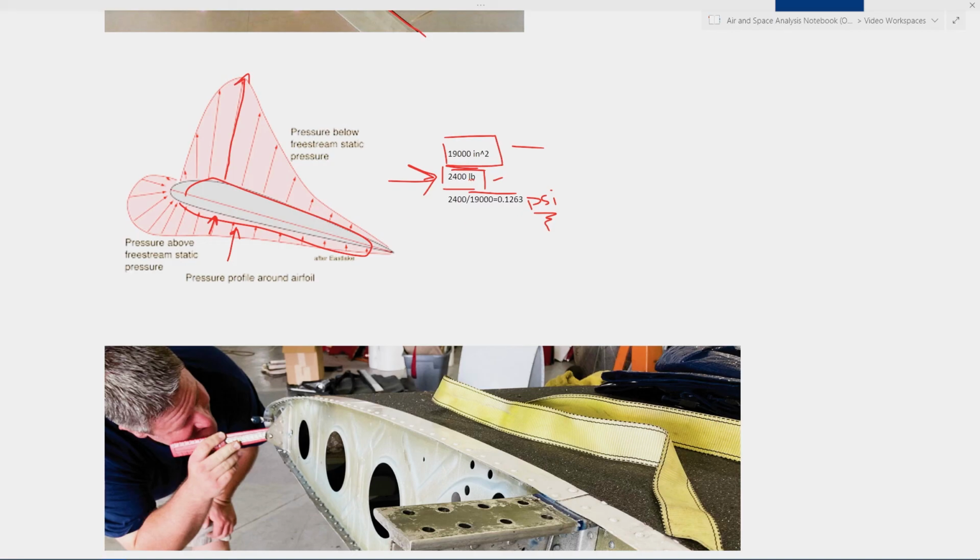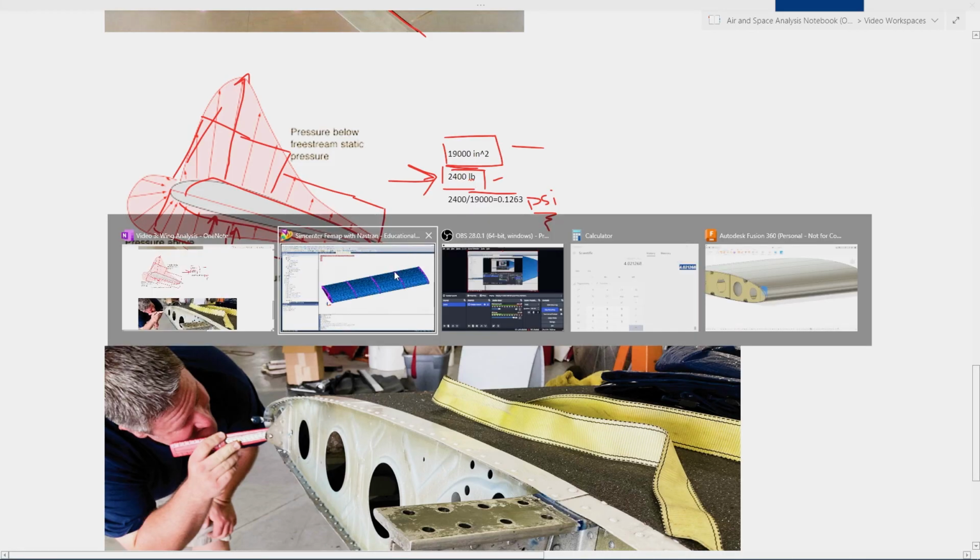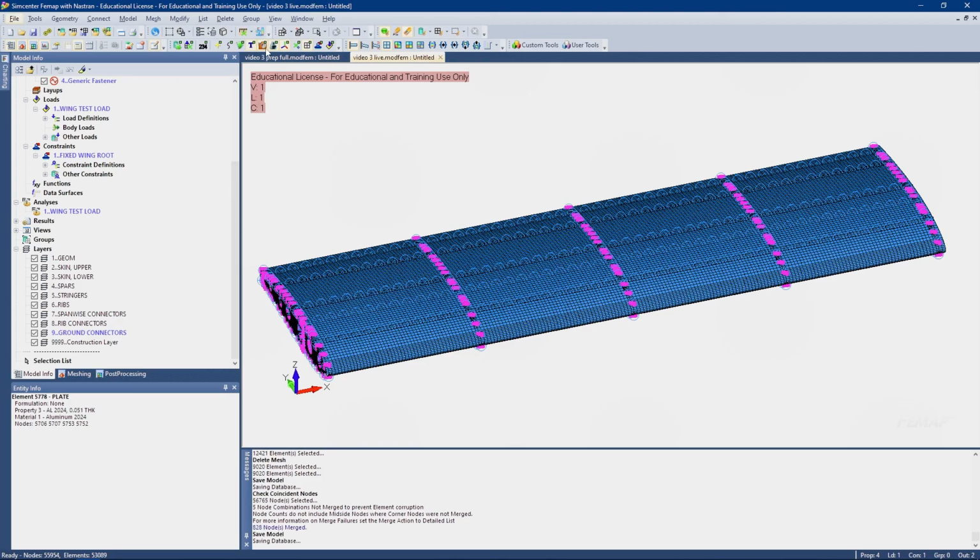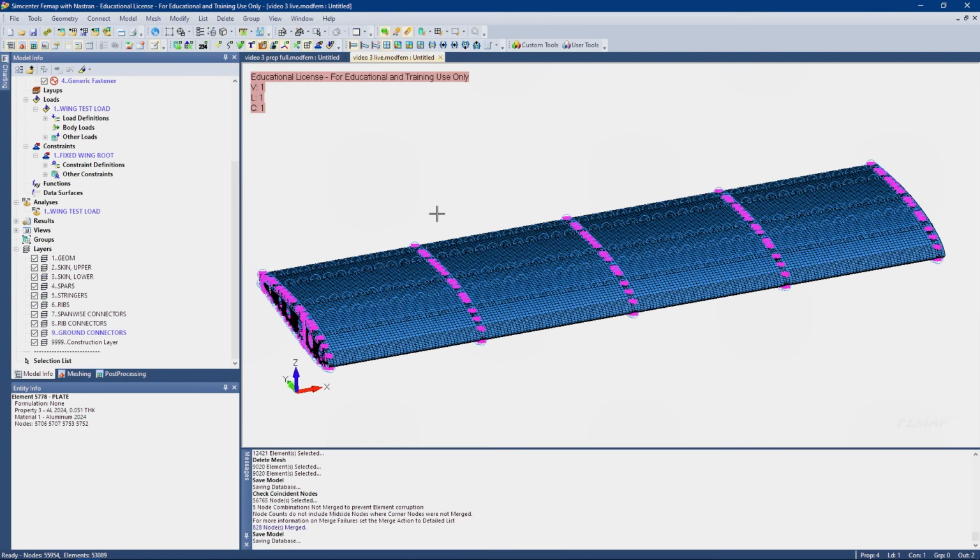So we're going to also vaguely approximate this curve. We're going to put, I think it's 0.125 on the front section, and then we're going to put 0.075 on the rear section. And then that'll get us roughly 2,000-ish pounds, which is what we want. And like I said, in a future video, we'll revisit this to generate a more accurate pressure curve.